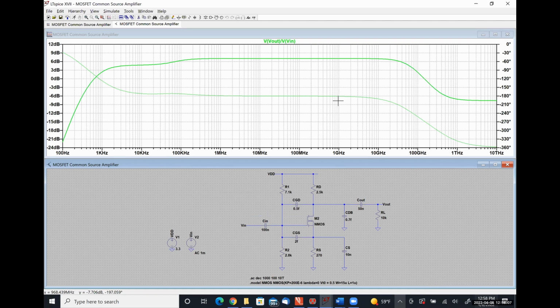So the parasitic capacitors that are introduced by every single little chunk of that high res poly form a parasitic capacitance with the substrate, because it's a layer of polysilicon on top of the substrate. Every one of those has a parasitic capacitance. There's a bottom plate capacitance formed between the bottom plate of your poly 1 to poly 2 capacitors and the substrate that are parasitic capacitance that are messing with things. And what that's doing is pushing that high frequency roll off further and further back. The more parasitic capacitances we add, the shorter the bandwidth of our system is. So anyway,